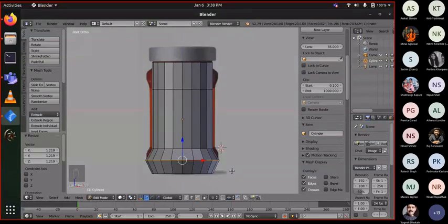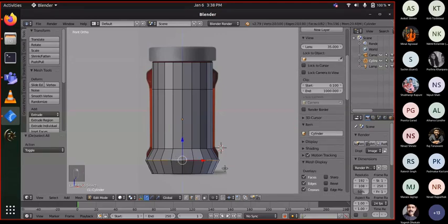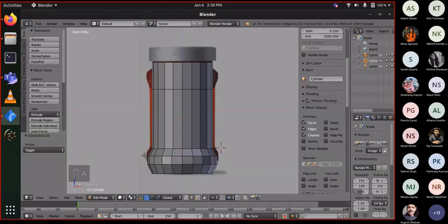Now the other operation that we are going to perform is to select the same thing again, and now we are going to bevel it. Beveling is the process wherein you smooth out the edges, the sharp corners that are there. As you can see, it is just a sharp corner around the edge loop that we have selected. Now when we bevel it, some additional faces are generated so that the shape looks more like the one that we have in the picture around us.